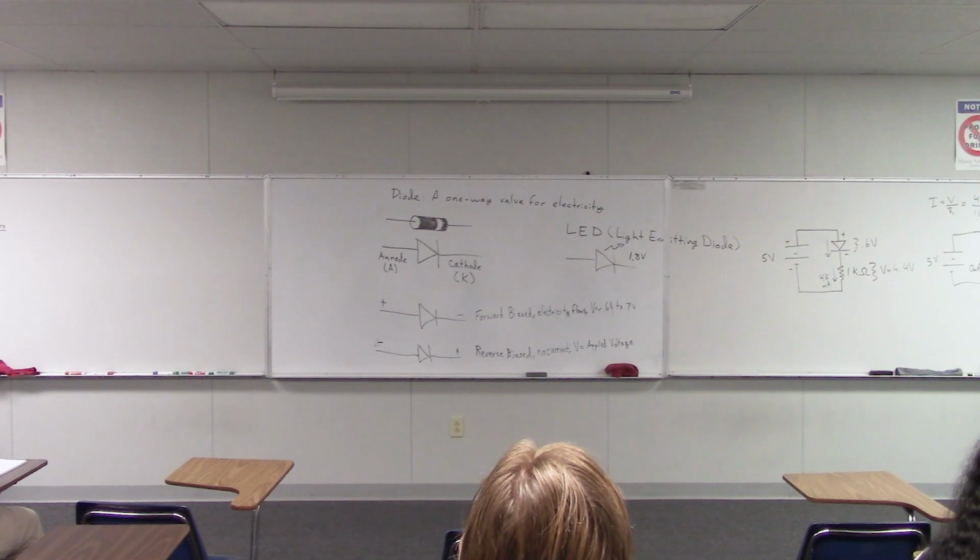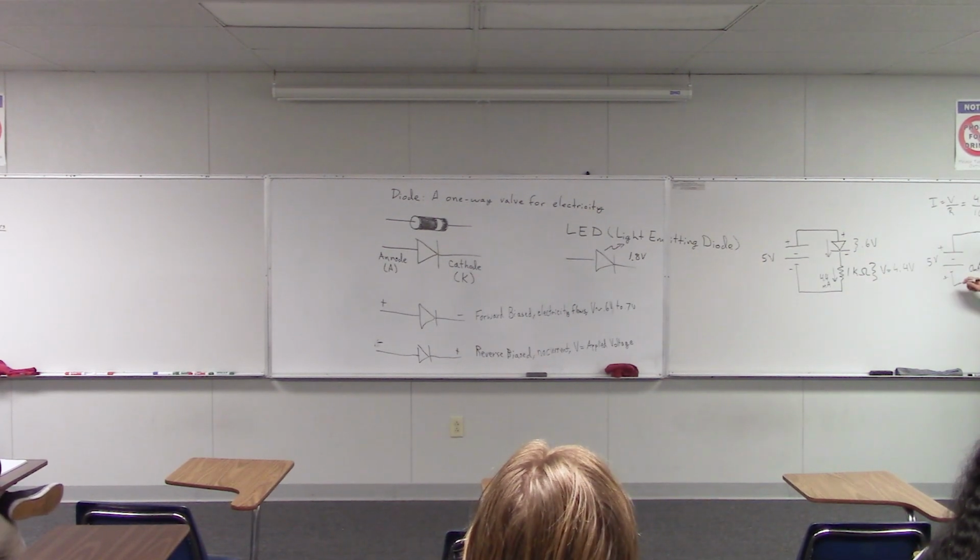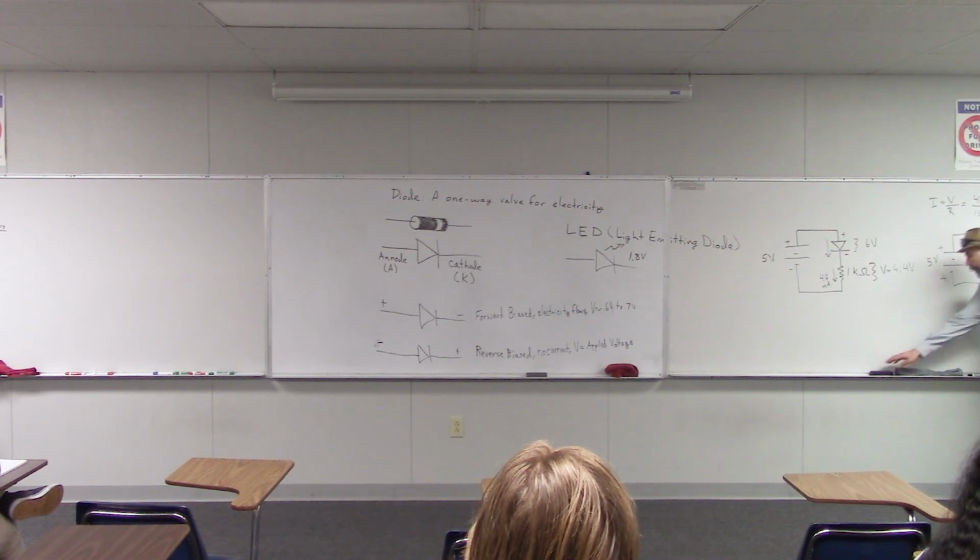So that's why you get all of the applied voltage across the diode when the diode is reverse biased. What would be the purpose of doing something like that? Well, again, this could be like in a protection circuit. When the voltage is plugged in the correct direction, the diode is reverse biased, and none of the current flows through there, and maybe your load is over here.